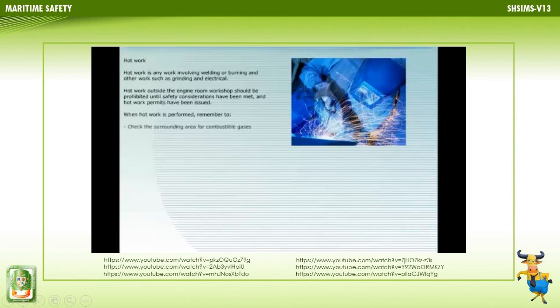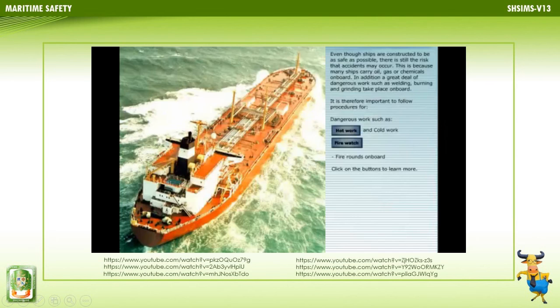When hot work is performed, remember to check the surrounding area for combustible gases. Always have a fire extinguisher close by. Always have a fire watch posted.